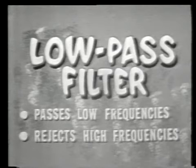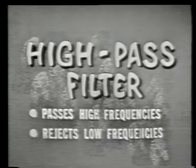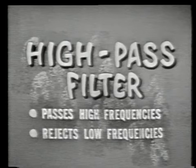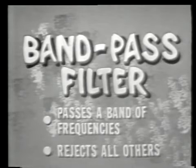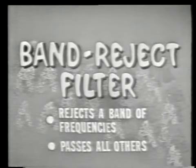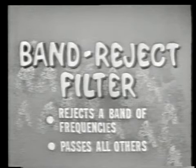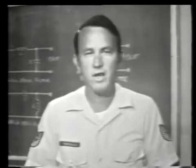One, to pass all frequencies below a specified value and reject all those above that value. Two, to pass all frequencies above a specified value and reject all those below that value. Three, to pass a selected band of frequencies while rejecting all others. And four, to reject a selected band of frequencies while passing all others. All electronic filters fall into one of those four categories, except for a few very specialized cases.